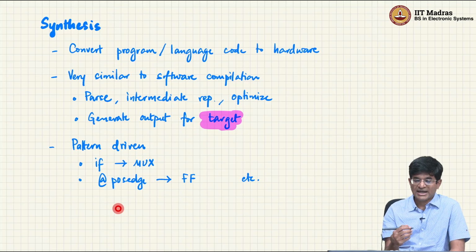But that is the process of synthesis, and if your code has been well written and your modules have been well designed, and if they passed simulation and if they pass through synthesis, hopefully the final set of gates that you get will also be able to pass the same simulation, since after all we can model the same gates in simulation in Verilog itself, and when you finally build the circuit out of it, they should behave as expected. The important point is the language by itself does not guarantee any of these steps, right. It pretty much says, okay, yeah, there are certain ways, if you have written your code properly and not tried to do some kind of strange use of the language that it does not normally support, you should in most cases end up with a scenario where everything synthesizes properly and works as expected, but it does not guarantee that unless you have followed the procedures properly.